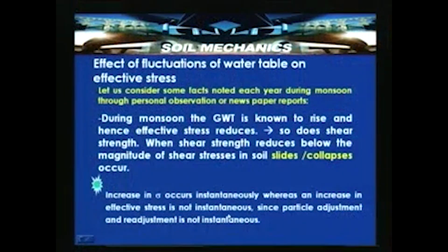One thing we should note is that an increase in total stress sigma occurs instantaneously, whereas an increase in effective stress is not instantaneous, since particle adjustment and readjustment is not instantaneous. So, the change in effective stress is not an instantaneous phenomenon.